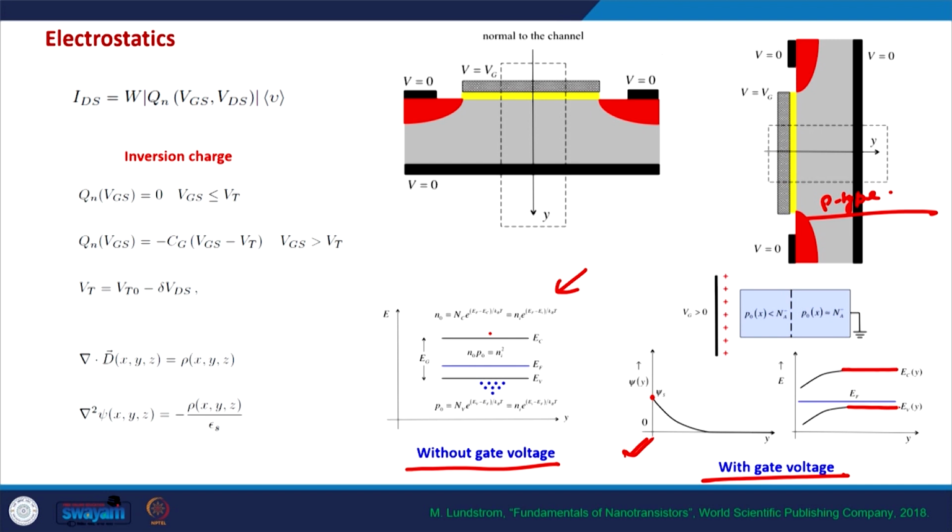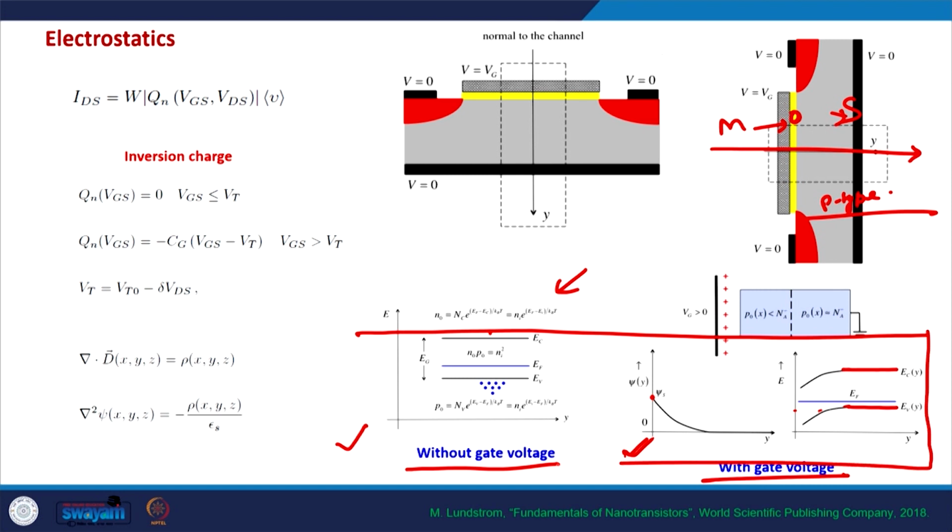The Fermi level is quite close to the valence band in the semiconductor, but close to the interface between the semiconductor and the oxide, because of the depletion of the holes, the Fermi level is now removed from the conduction and valence bands, and this is how it looks. Generally these bands are drawn for this MOS device. M means metal, which is the gate, O means oxide, and S is the semiconductor. So these bands are representative of the MOS electrostatics: metal oxide semiconductor electrostatics.